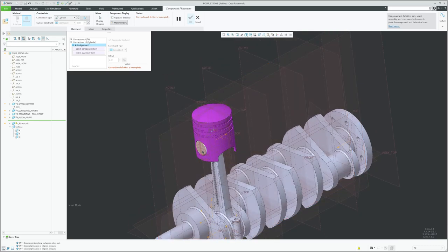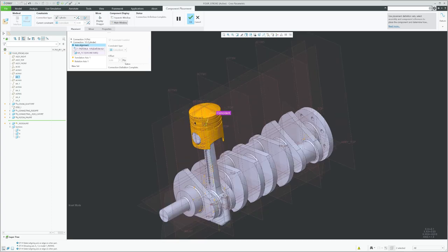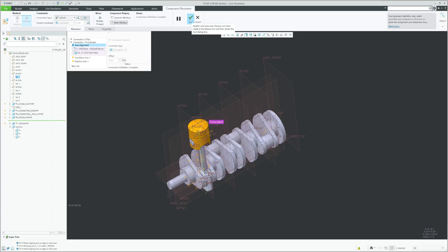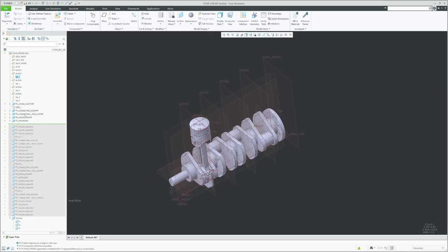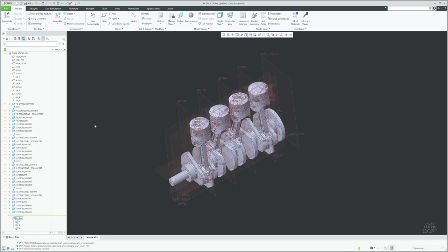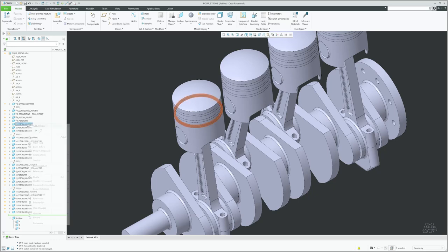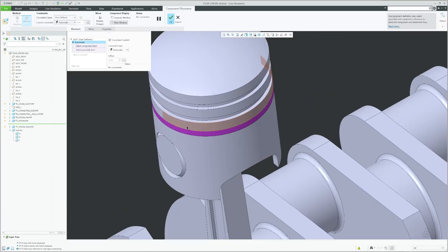So what I'm going to do is to align the piston axis and the piston, and the axis that we created just at the beginning of the exercise. So I will click OK. Then I will activate all the components, and these are really easy to complete. So I will deactivate all the references and the piston ring. I will edit definition. So this one can be general.